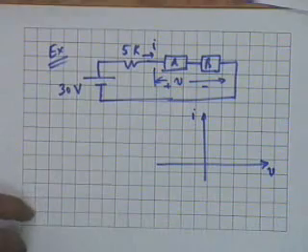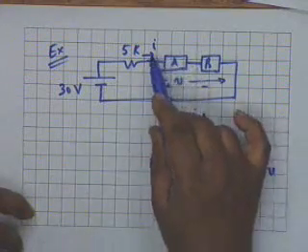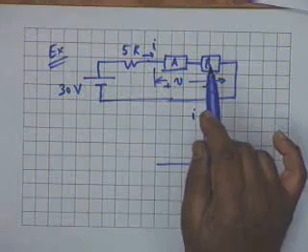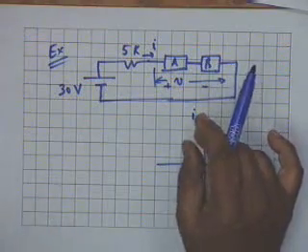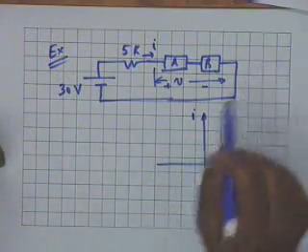How do you do that? Add the two graphs. That is, you know I versus VA and you know I versus VB. So set a particular I, read VA and VB, add the two, and plot a new point. Let me show you. I have actually done this.